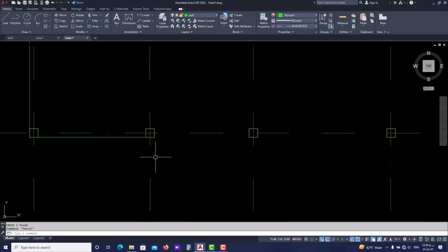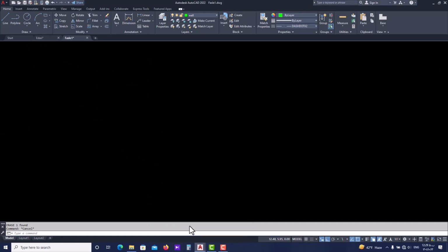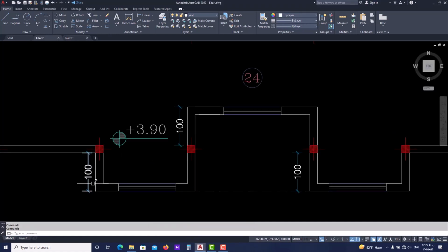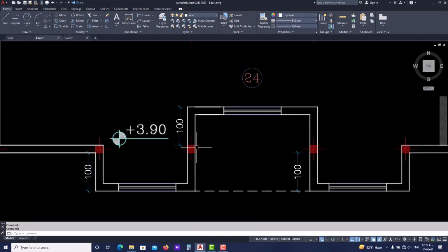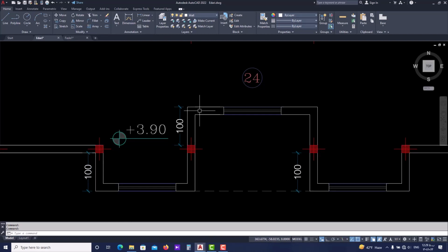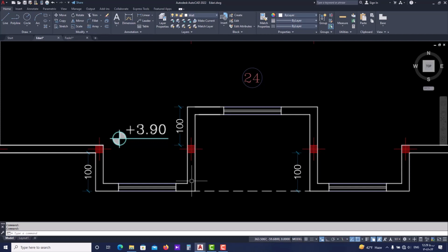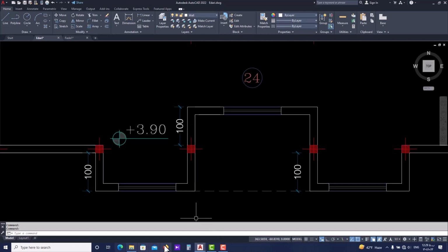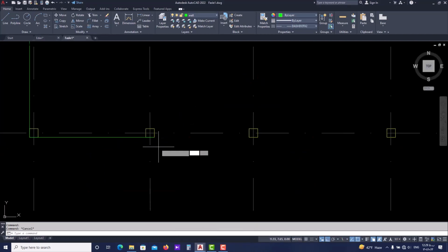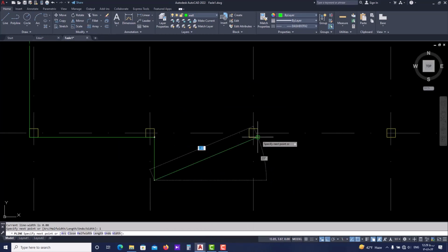So let's go back to the plan. Here that we have this neck here, this 1 meter neck here. Because we are working on an exterior wall, for this part, we need to subtract the wall's thickness from it. So instead of having a 1 meter neck, we would have 80 cm. So PL again, 1 meters down.